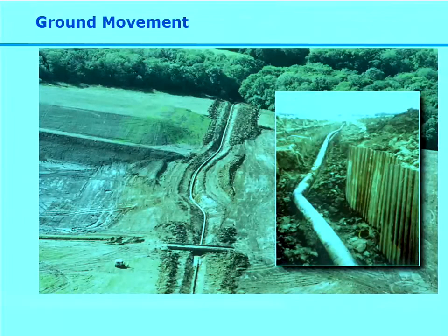And the reason they had to repair it was, if you look at this one, this is a different pipeline, but it shows you the problem. This is actually a pipeline that was excavated so that it wouldn't receive any loading due to land subsidence, which was occurring because of mining underneath. And what happens here is, if you excavate too quickly, the pipeline moves quickly and it kinks. And the kink, of course, is a structural failure which you've got to repair. And that's what had happened to the first pipeline. It had a couple of kinks in it.